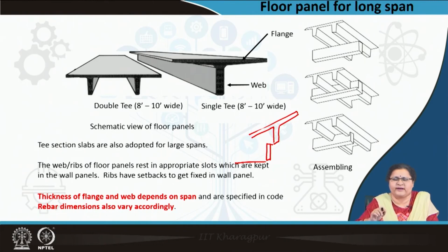So, when we are plunging into the prefabricated world, we have to follow specific rules, specific nomenclatures, we have to know the codes, what is the specification, and we just cannot make a wishful dimension. We have to look into how big these can go up to, and what is my requirement and which is the closest in dimension, and we have to design accordingly.